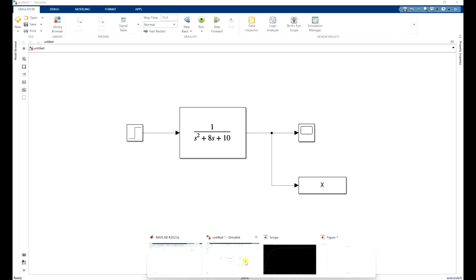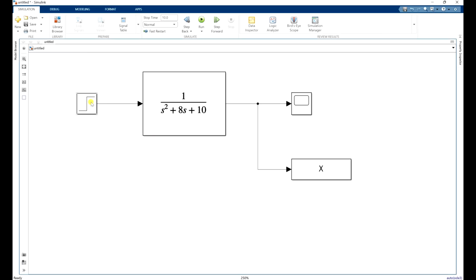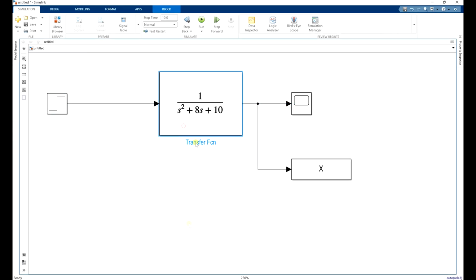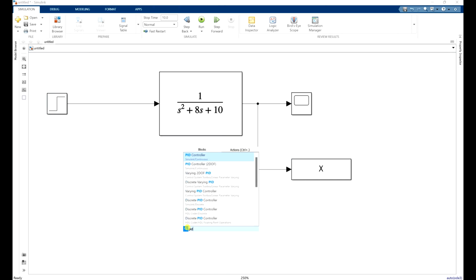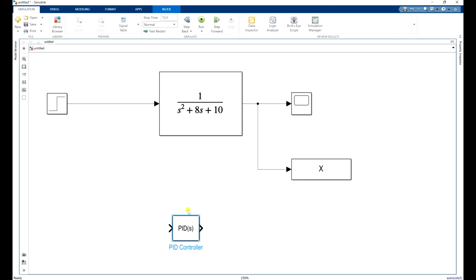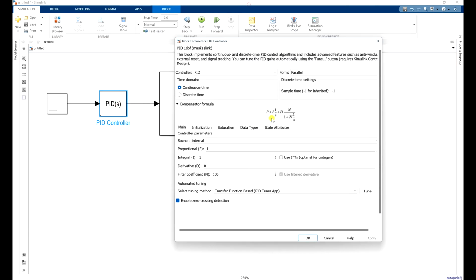So I'm going to go to MATLAB here. Okay, like this, and then type PID controller. Okay, and then I'm going to add the three gains, 17.6, which I obtained by substituting, and the integral is 126, derivative is 0.61775.